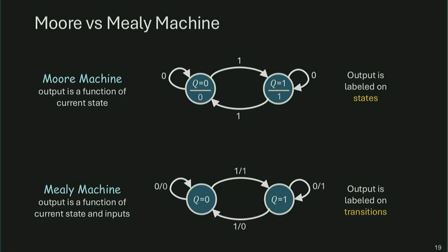We start from some behavior description, like a parity counter, and then we first need to model it as this kind of a state diagram. This is a formal model that clearly represents all the input-output behavior without any ambiguity. And subsequently, we need to convert this graph into a circuit implementation through a different layer of translation. So there are many layers of translation happening.